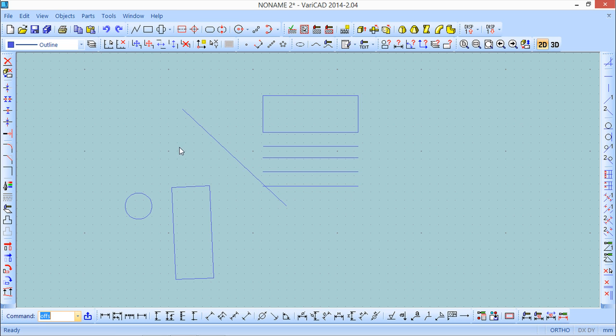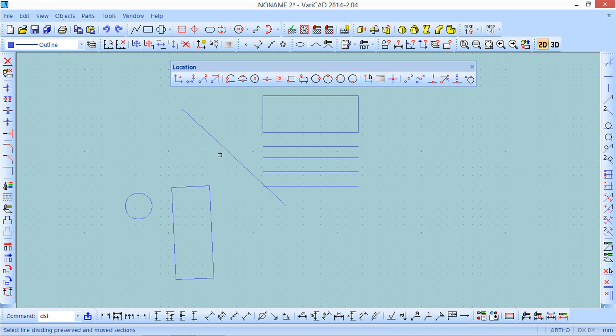To end this, I still have another function that I would like to show you, but to call this function, I need to write in the command line the DST option that will invoke this command. So when I say DST enter, I have these 3 possibilities that basically are the same, so I will show you just one. And this is a possibility to make stretches, horizontal, vertical, or diagonal. So let us try the horizontal one.